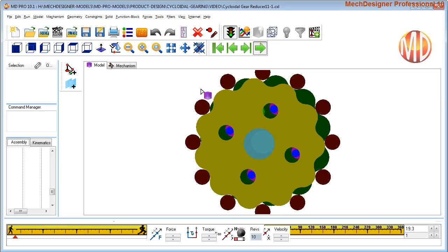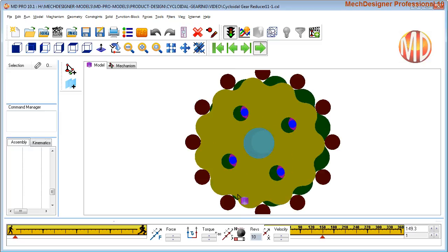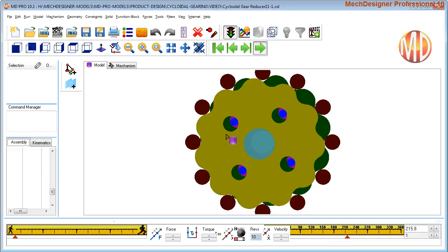And so that disc is slowly rotating, but it's also wobbling. So one of the tasks is to get out the rotating motion and eliminate the wobbling part of the motion. And we do that by cutting holes through the discs and engaging it with a set of pins that are on the output rotor. And the output pins rotate at constant speed without the wobble action.